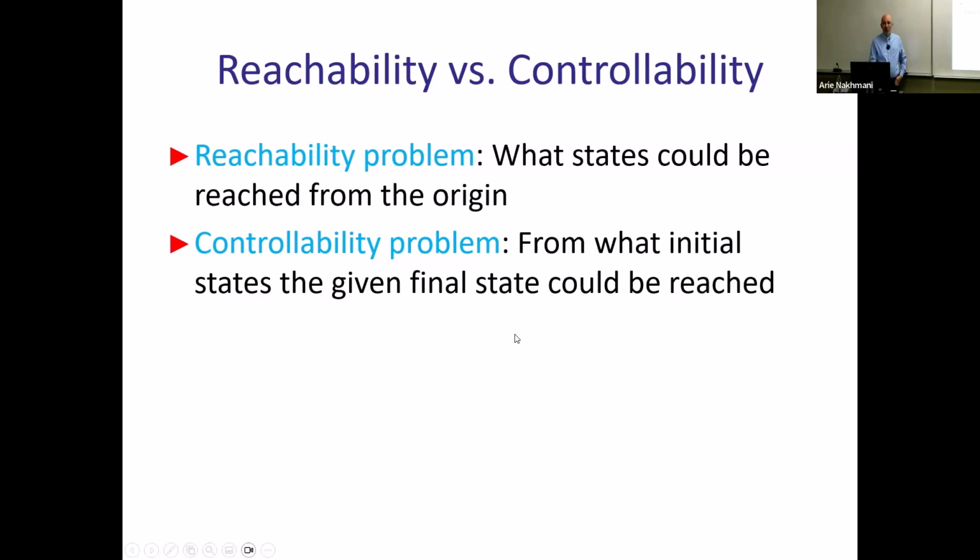because you have additional terminology that people sometimes use in that theory. For example, reachability, because we are talking about what states we actually can reach. And the idea of reachability is where you can reach from the zero state. Like if your x0 equals 0, the origin of your n-dimensional coordinate system, where can you get with your system? So if the system is controllable, you can get anywhere. So it's obvious. But if it is not controllable, you will be able to get only to the span of these columns of the matrix from 0, right?